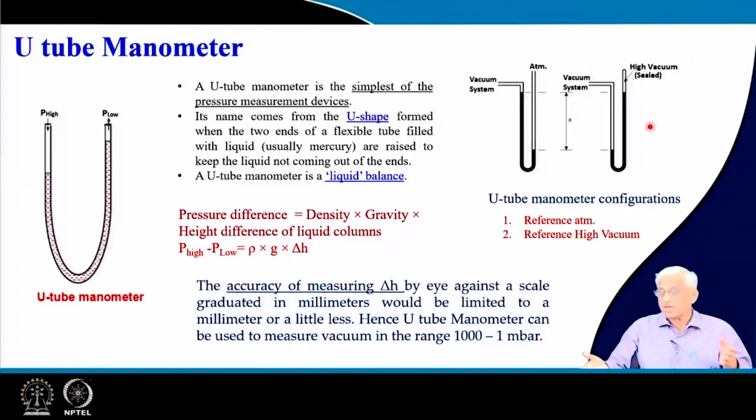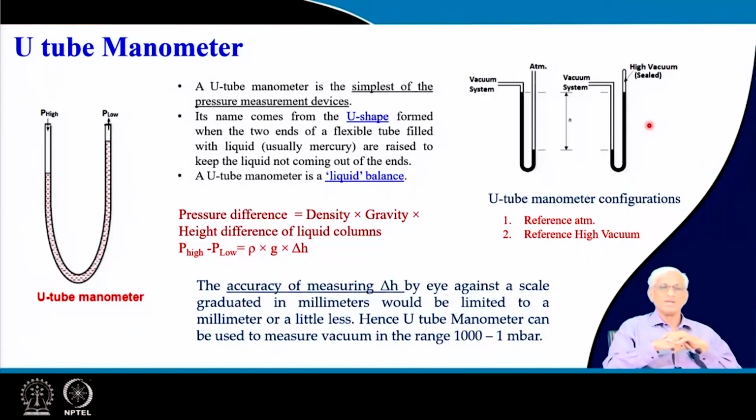And even if you keep very accurate instruments or a microscope or telescope, you cannot do that, because if there is a fluctuation or vibration, it may change. So, even if the levels are actually changing, the measuring sensitivity is not there, you are unable to measure. Okay. That is why you cannot use this U-tube manometer below 10 millibar. Even sometimes people say 50, 60 millibar. Below that we start getting errors, 5%, 10%.